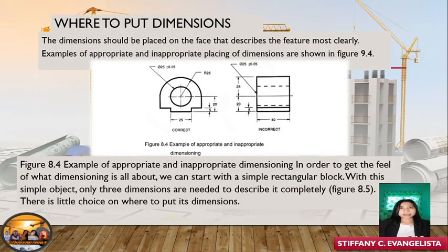So where to put dimensions? The dimensions should be placed on the face that describes the feature most clearly. So it is important to remember to place dimensions on the views in a 2 or 3 view drawing where they will be most easily understood.